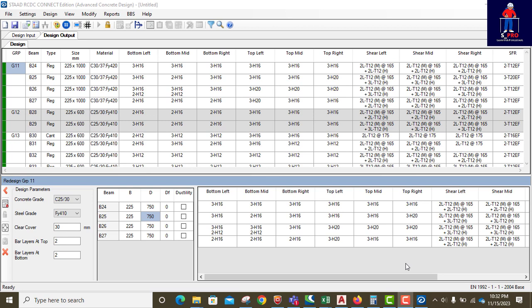So you can go back to your model and look for places to put more columns under those beams, and of course it's not going to stop at the first level. It has to continue because these beams are the same thing, and they are carrying the same load. The load from the slab is being transferred to those beams, and they transfer it to the column. So you get two options. Either you keep increasing the depth of this beam, or you go and introduce more columns under those beams. But let me just increase the depth so that we can end this course.